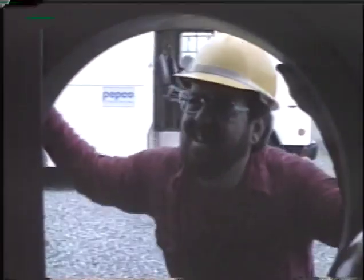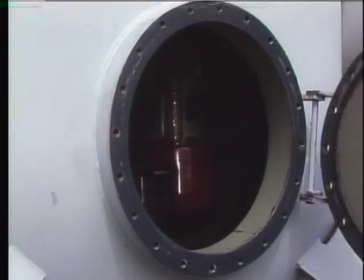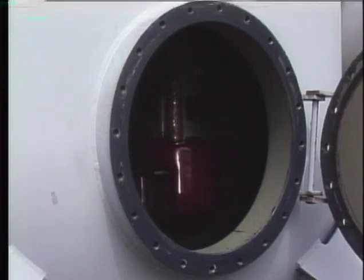After all the oil is pumped out, the breaker inspection door can be opened. Combustible gas may be present inside the tank due to arcing in the oil. Care should be taken to avoid igniting any gas that may be present. Allowing the breaker to air out or ventilating it with a fan helps to remove gas and also ensures that there is enough air to breathe when working inside the tank.